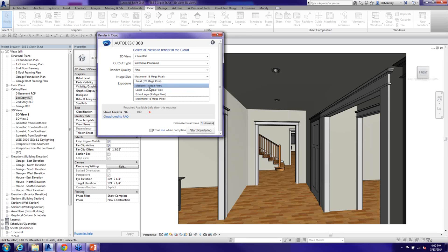Okay, so just go through and start looking at what you're doing here. It is requirements, and do pay attention to this. I had one client come in, and one of their users used up their 100 cloud credits in like an hour because the guy didn't do draft rendering, so he did everything as final. And, oh crap, I forgot to assign IES. Oh crap, I forgot this material. Within an hour, he went through $100 for the points.